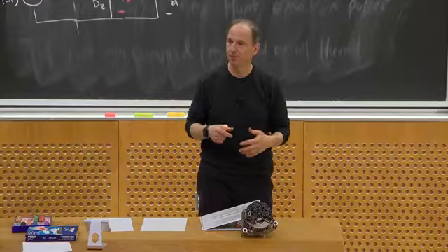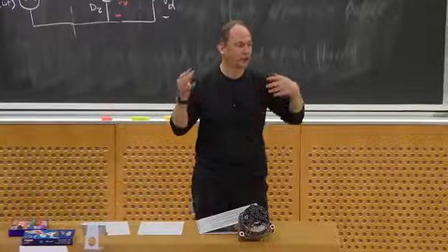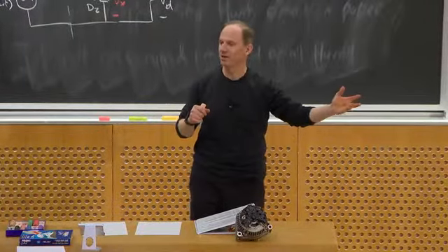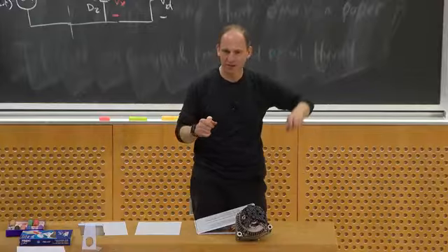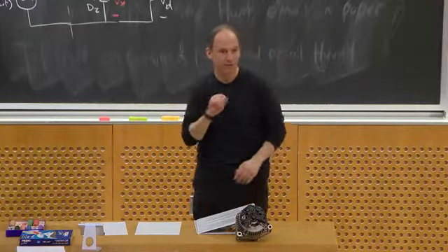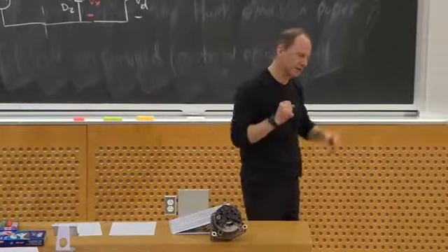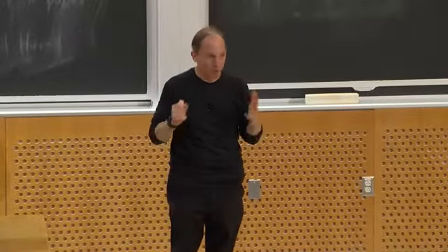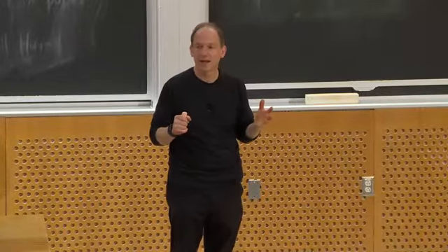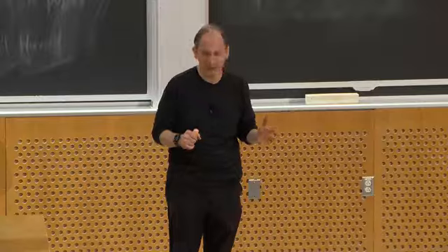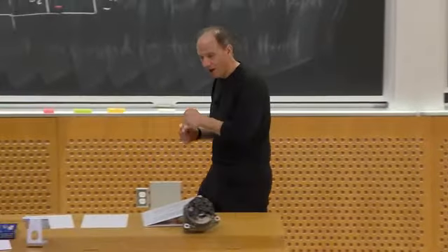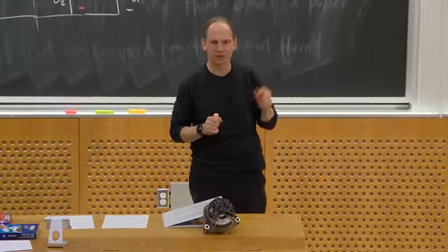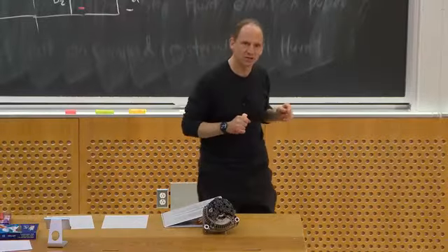It's also true if I build, as we'll see later in class, a high-frequency resonant DC-to-DC converter. What I do is I create really high-frequency AC signals, like a megahertz, run them through a transformer, and then rectify them in some kind of rectifier like that. Okay, it doesn't have to be that exact rectifier, but you do it. All right? In both of those cases, you may have inductance on the AC side. Well, why? If I'm plugging into the wall, I've got all the wall wiring going back, and then somewhere back behind there is a transformer which has what's known as leakage inductance.